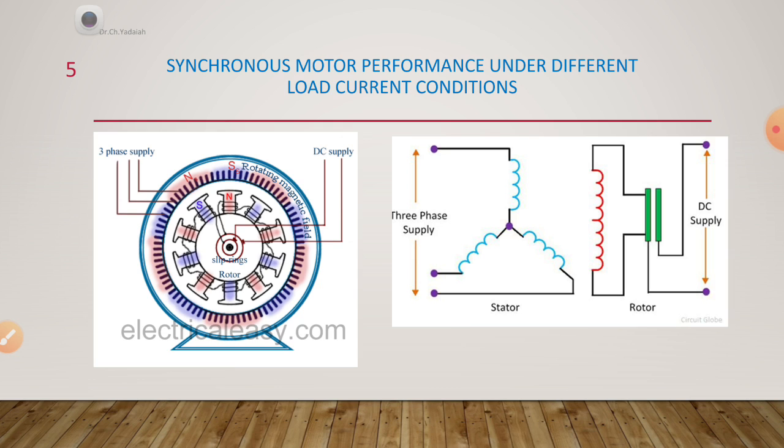So, you have to remember one thing. In case of DC, the back EMF is developed in the armature due to the EMF induced in the armature itself. The applied voltage minus the back EMF developed in the armature, that is the difference V minus EB, is the resultant voltage.